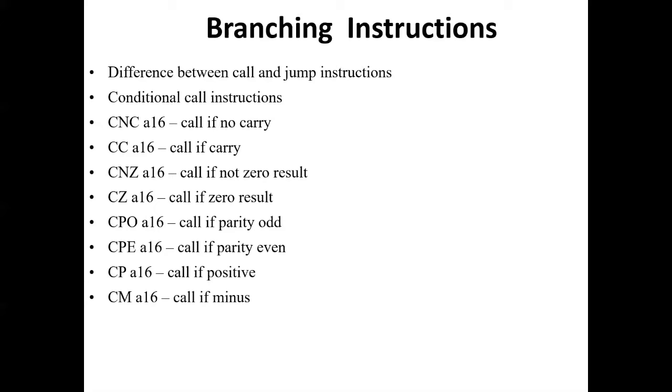Next is CP A16. CP is a mnemonic which stands for call if positive. This instruction is used to branch to the subroutine whose 16-bit address is provided in the instruction only if sign flag value is 0. If the sign flag value is 1, program flow continues in the main program sequentially.